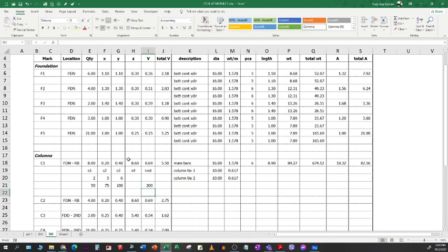Okay? Now, how do we make use of all of this? First, let's account for the standard spacings near the support. So, how many are all those spacings? We have 2 plus 5 plus 6, and then multiply it by 2 since there are 2 supports, times 2. Okay? So, we already have 26 ties near the support.